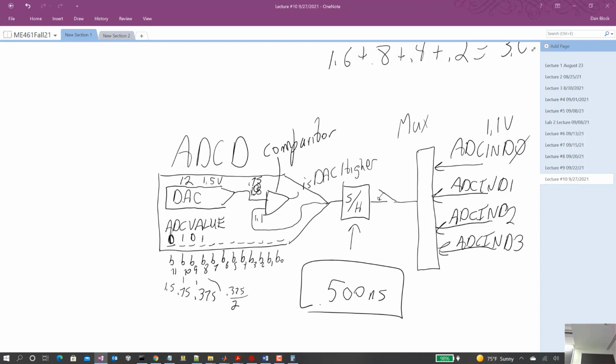And our DAC that goes out to the world does the exact same thing. This is half your range, this is a fourth of your range, this is an eighth of your range, this is a 16th of your range. And when they're all ones, add them all up. It's the full range. When they're all ones, 1, 1, 1, 1, 1, 1, then you've got 3 volts. Okay? Good.